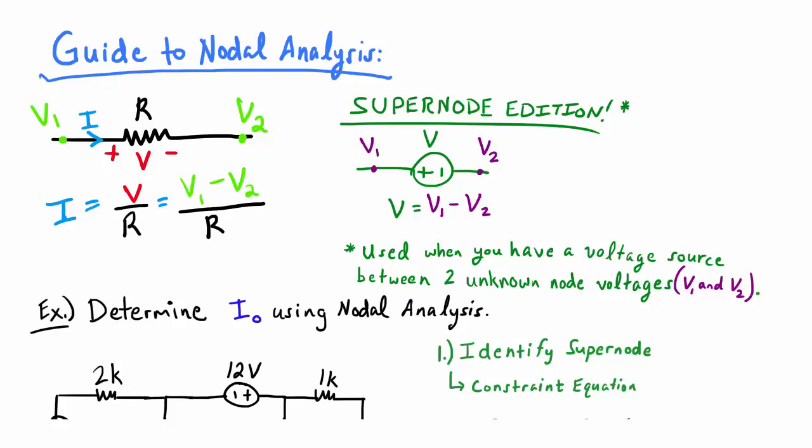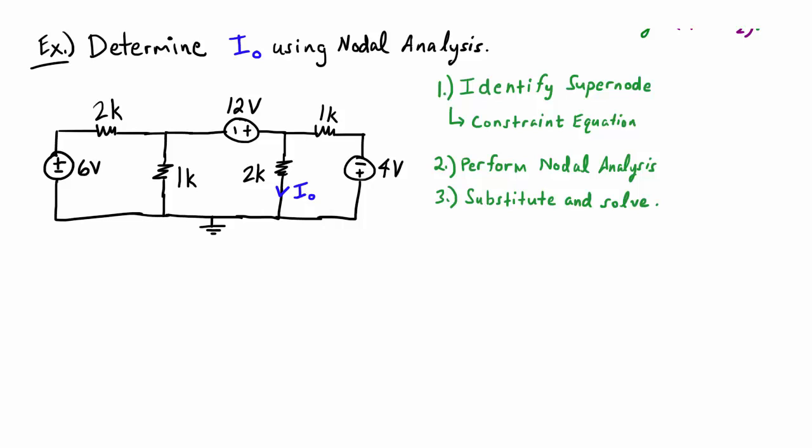Okay, so this example will involve the use of a supernode. Now on the right here, I've given you a little three-step process for using supernodes in nodal analysis. So the first step here is to identify the supernode.